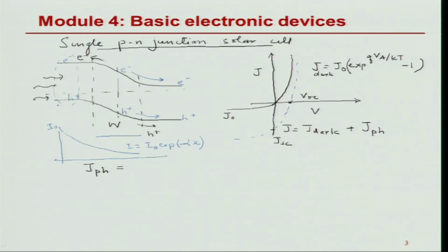So they may recombine or drift or diffuse in either direction, but there is a region close to the depletion width, which we define by the diffusion length of the minority carrier on this side. Similarly, there is a region close to the depletion width, which we define by the minority carrier diffusion length on the n side.